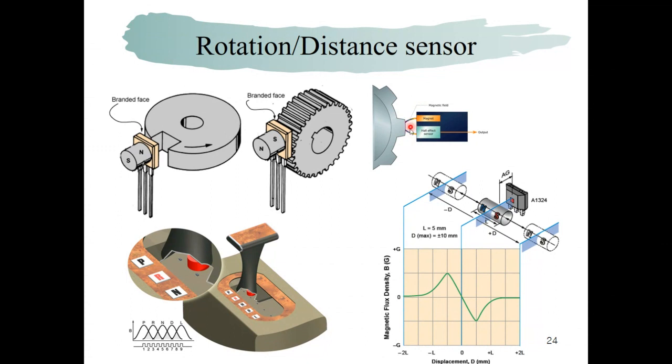Because, as I already mentioned, with this magnet sensor we don't need this part to be very clean. If there is some dust and some kind of oil, it still works. But if we are using, let's say, an optical sensor, they are very weak against dust, or if you cover it with some oils and some kind of lubricant, the optical sensor will malfunction.